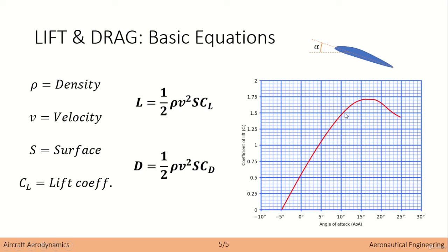What else? I wanted to point out that, as I mentioned, the coefficient of lift is around 0.5 to 1.5. The coefficient of drag, which I haven't drawn here and will explain later, is around 10 times less than the lift. So if lift is around 0.5 to 1.5, drag would be 0.05 to 0.15, something like that. So a magnitude of 10 is the difference between the lift and the drag.